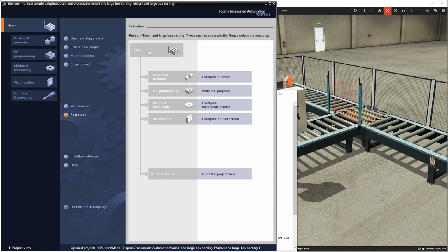So too is the input offset start address, because we can't actually use the factory I/O input addresses on the PLC as they don't exist. However, this is one of the benefits of using factory I/O, in that you don't need to have all the physical inputs on your PLC and can make do with a smaller PLC.